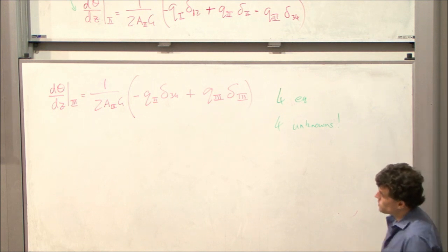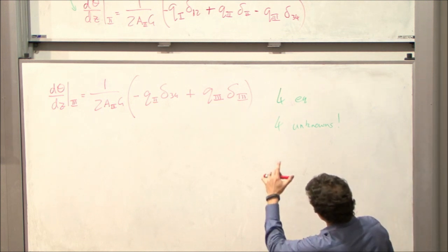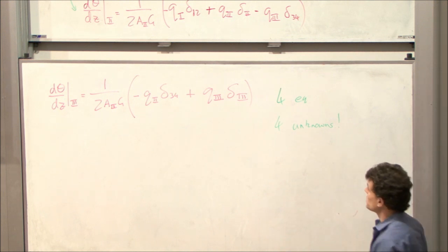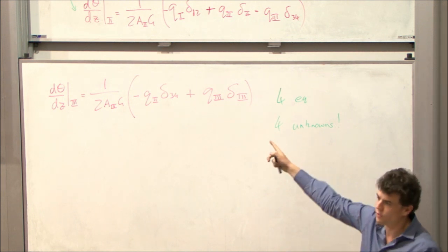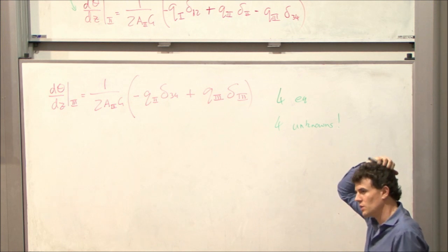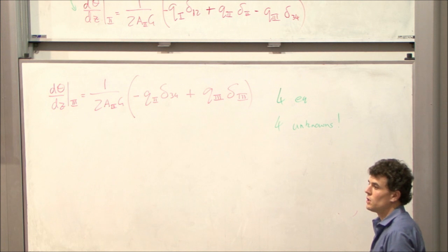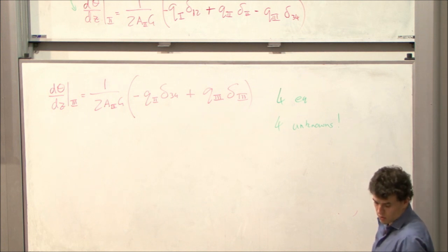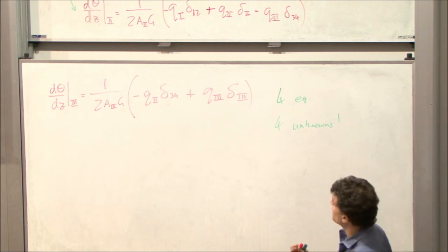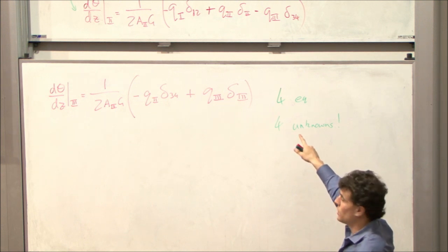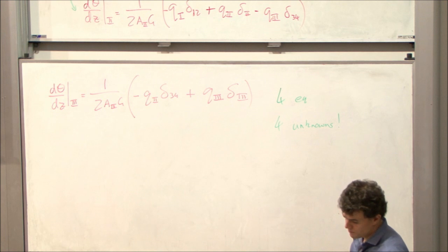There are some tricks. Once you've done a few of these, you can work out what terms to sub in to get rid of certain things. The first thing in most problems you want to get rid of is the rate of twist, because the rate of twist is less interesting to us than the shear flows that are in the section. So Megson doesn't show the simultaneous equation solving for this problem. He just says it can be done.